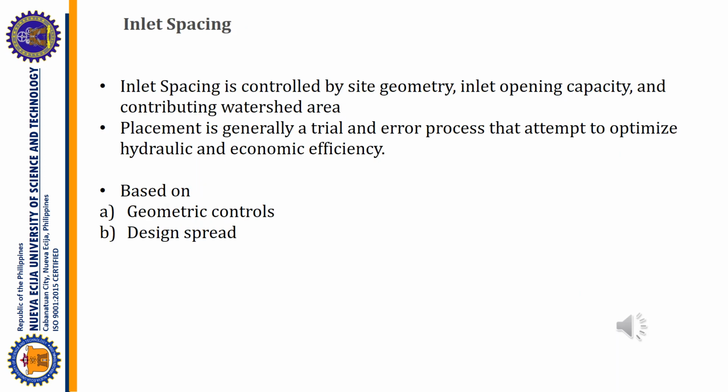So, inlet spacing nga daw po is, number 1, inlet spacing is controlled by site geometry, inlet opening capacity, and contributing watershed. Number 2, placement is generally a trial and error process that attempts to optimize hydraulic and economic efficiency.